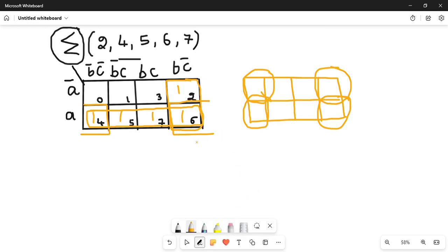Okay, so the grouping will not happen. So this overlapping group will not be possible. Why? Because this one already has a 1 in cell number 4, so the one in cell number 4 is already shared with this group of 4, and the one in cell number 6 is shared with this group of 2. So it has been shared by the cells. So that is why it becomes redundant. So here the overlapping procedure will not come into existence.